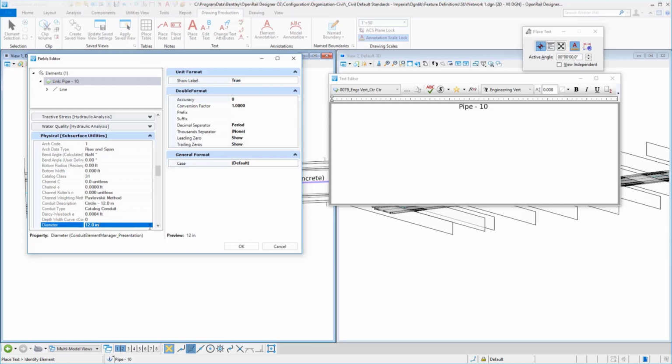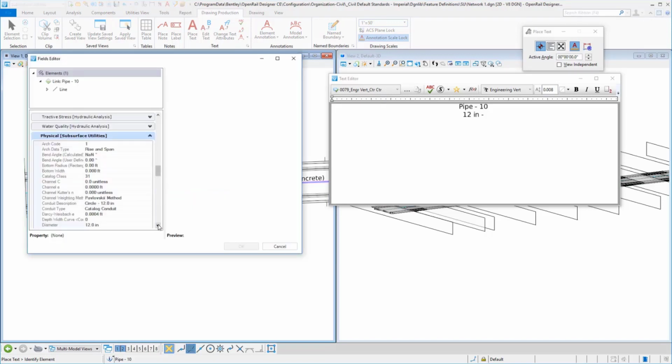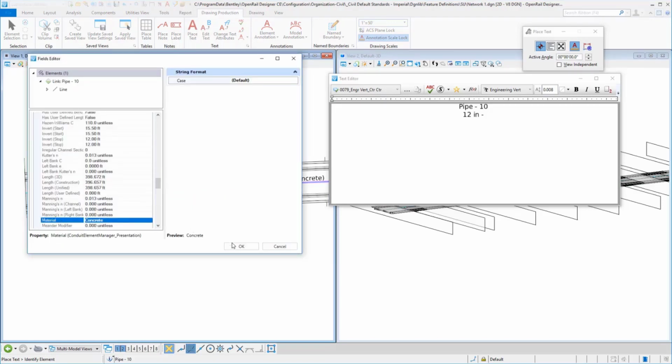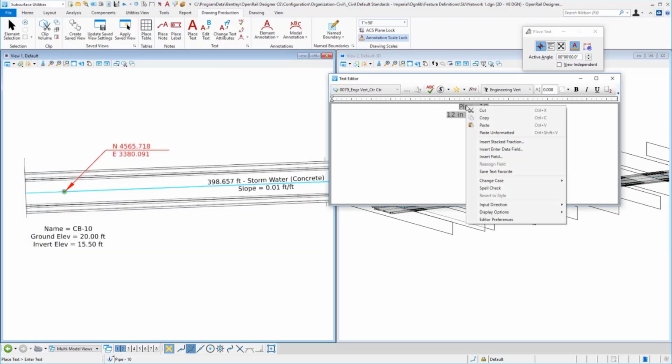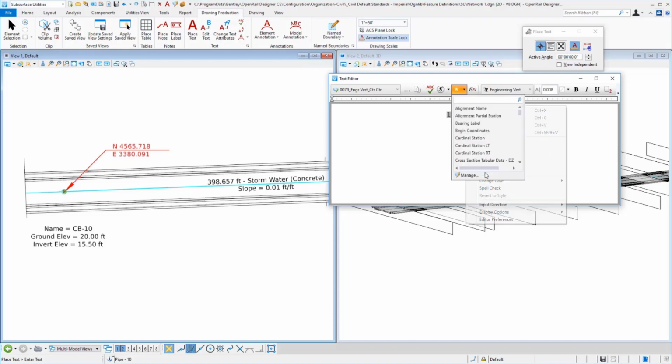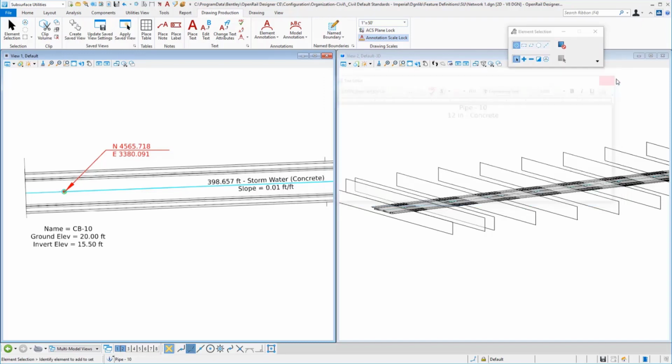You can set properties there additionally if you want, for example, accuracy. I'm going to put in a separator here, a dash, and then go back to my insert fields. And in my insert fields, I'll pick my pipe again, and I'm going to scroll down in that same category to material and select OK. I'm going to select all this with my mouse, right click, and create text favorite, and accept that, and then go back into my drop down list. I'm going to rename that something like Sue XS, link name, diameter, type. Then we're going to close our text editor.